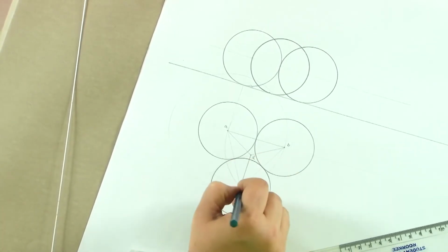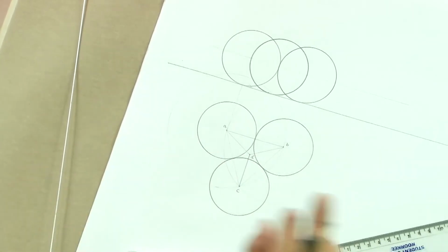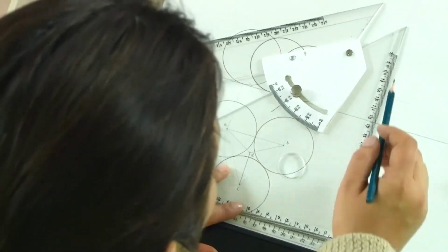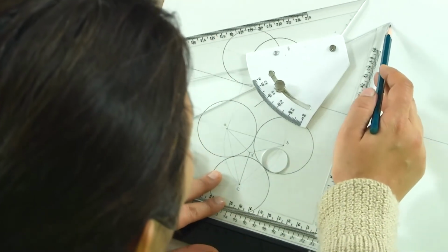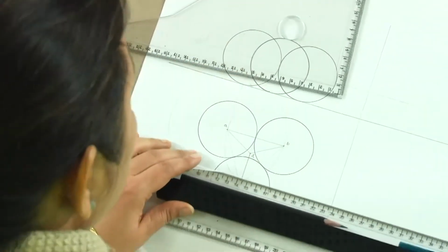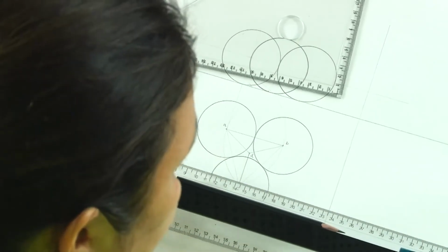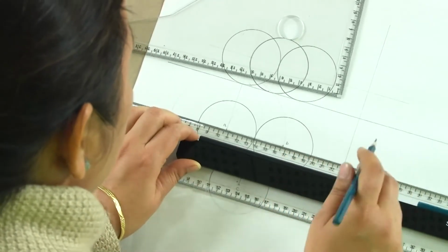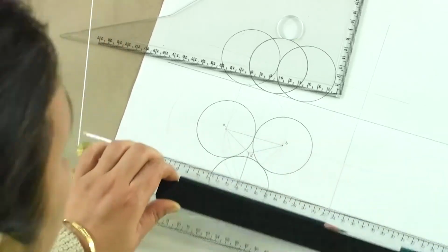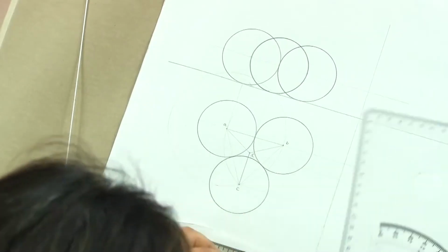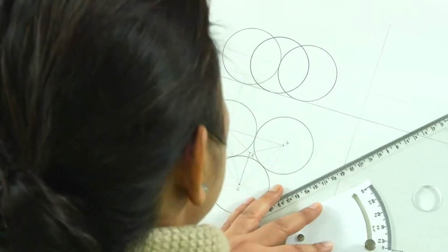It is making an angle with both HP and VP, but we have the side plane to which it is going to be perpendicular. So all we have to do is take this line DC onto the side plane. So just like we did earlier, we will project it onto the side plane.